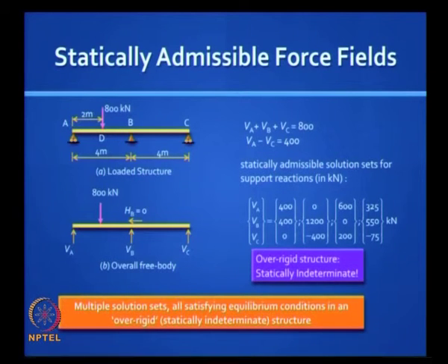which means you will probably get a deflected shape which looks like, can you see the first deflection shape, the dotted line? That means there is no contact. It is like there are supports only at A and B, and the beam will definitely lift off from the support C. Then you could get this solution, there is nothing wrong with that, but it is not kinematically admissible.